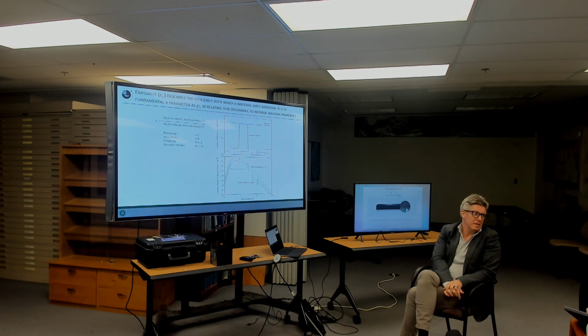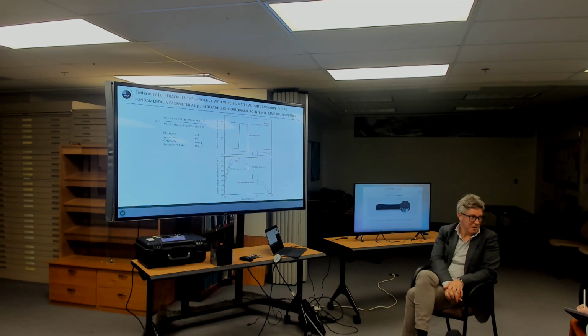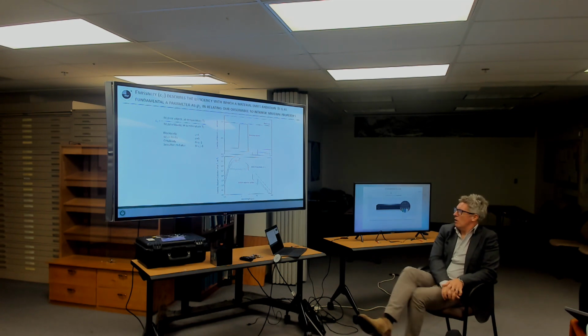So if you remember with spectral reflectivity, we said spectral reflectivity is the amount of light reflected from an object over the amount of light which landed on the object. Right? So to compute reflectivity, we were relating the energy reflected by an object to another amount. We were normalizing it by something else, and we normalized it by the energy which struck the object. Here we're going to normalize the energy which left a real object by a standard, and that standard is the energy that should leave a black body at the same temperature. Right. So if we just plot that up.